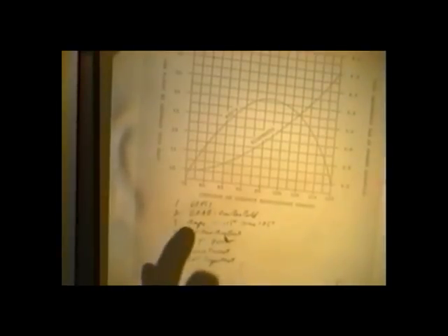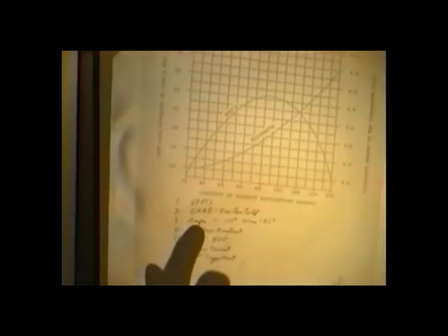We also would teach our younger people to grab the suction line and just continually add gas until the suction line is cold, and of course how cold? Until it's beer can cold. And I've got to tell you, ladies and gentlemen, I have a book at home that actually tells us how to do that. That book goes back, it's probably 35, 40 years old. We also talked about charging. Oh, let me stop there a minute. Let's talk about that charging to beer can cold.